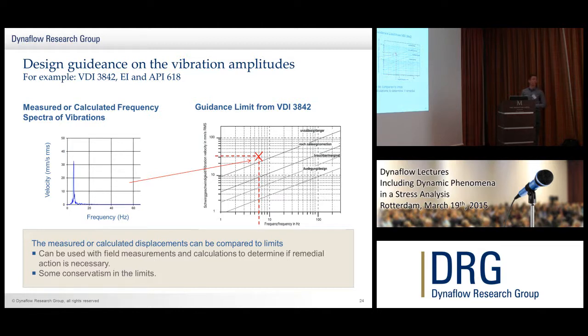So this is the German code, German guidance code, for assessing flow-induced vibrations. Okay. There's also a similar graph in the Energy Institute document, and there's also one in API 618 for assessing pulsations. Okay. And what we'll do is plot this on the graph, and we see that we're lying in what's called the danger region, meaning our system does not follow the guidelines from the VDI document. Okay. So the next question is, if we don't conform with this limit, what's the next stage?